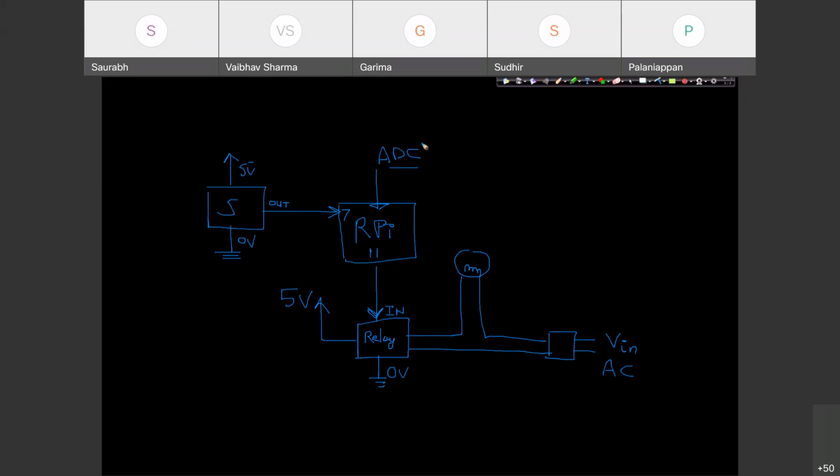So you need an analog to digital converter, right? If you have any sensor where digital output is not coming, where you don't get only high or low values from the sensor, and you want your data to come in a range instead of digital values, say between 0 and 1000, then you have to convert your data with an ADC before entering it into Raspberry Pi. And even after you have converted that data through an ADC, the direct output from the ADC will not be taken care of by Raspberry Pi until a communication protocol is implemented. So there is too much work on that side once your sensor is analog.